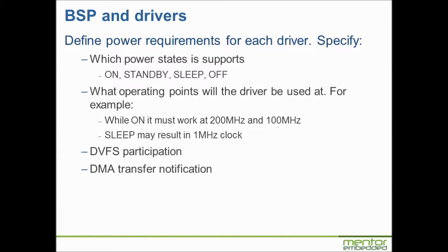That sounds perfectly reasonable, I suppose. And in sleep mode, it may need just a 1 megahertz clock, which is a drastic reduction in power consumption. We need to know whether a driver can participate in DVFS. In other words, it may have an influence on DVFS, or it may simply need to be informed that the frequency has been changed. The last one's more subtle, and that is direct memory access.